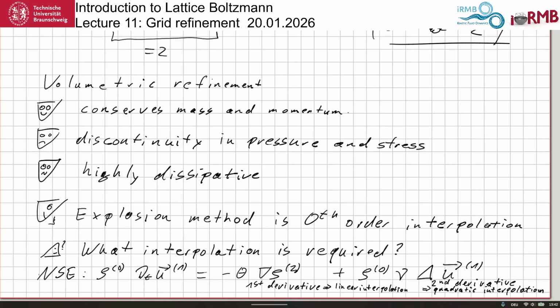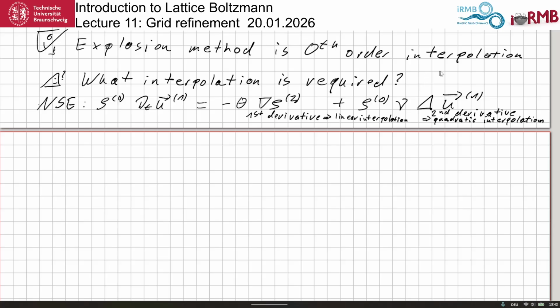So the practical observation, I mean, you can ignore this, and it will work. What happens if you use linear interpolation in velocity is that this equation is no longer balanced, and then the pressure will adjust this imbalance.